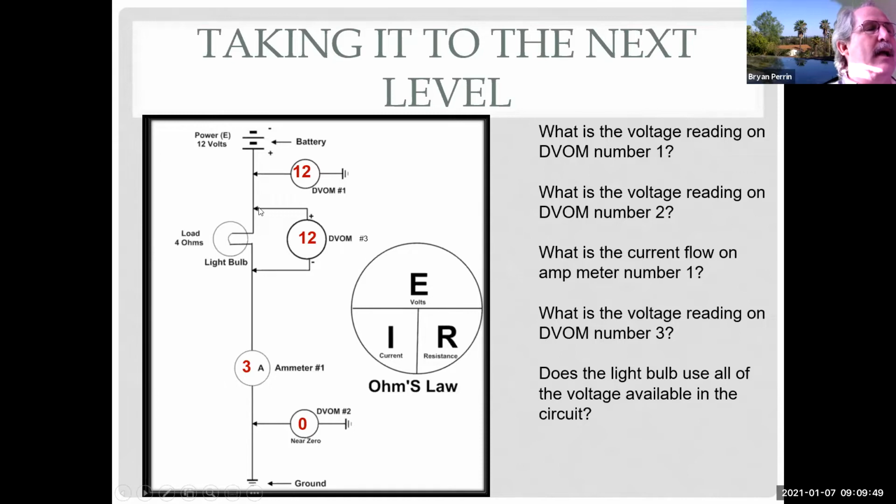So that is why a lot of times when we're testing something, we just take the voltmeter and test the voltage across the load. Because if I went across the load and only had 9 volts, I instantly know I have a problem somewhere else in the circuit.